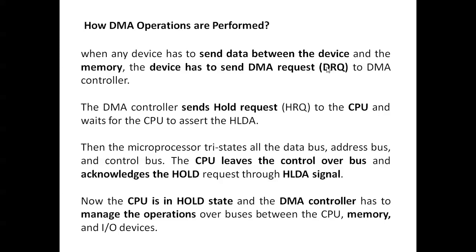The CPU, the microprocessor, leaves control over the data bus, address bus and control bus, and acknowledges the hold request through the HLDA signal.